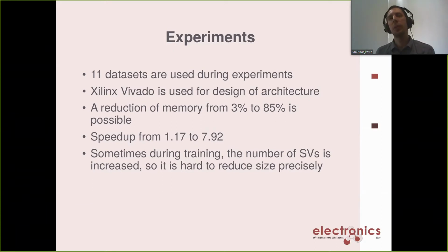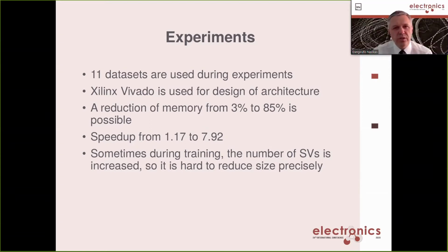If you want to implement something in an embedded system, you almost always have to lose some precision, because in PC models you use the floating point representation, and in embedded systems you almost always use fixed point representation. That's the reason to lose some precision. So that's normal. And can you say, is your solution more or less sensitive to the training set size?